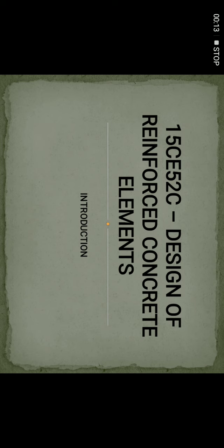Hello students, today we are going to see about materials like concrete and RCC. Before entering the subject, we have to know about the materials used in plain cement concrete and reinforced cement concrete. Plain cement concrete consists of cement, river sand, coarse aggregate and water.